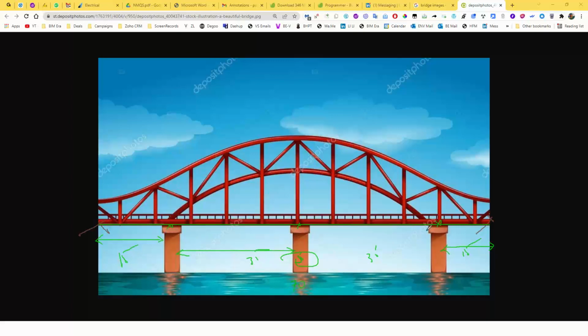Well, now this is the fun part. How to get these points? Using a point by parameter. We are going to see that now. I have a curve or a line, and I want to create a point at some parameter values. So this 15, this 35, this 35, this 15, we generally call these parameters. Remember, parameter here does not mean parameter names or anything. If you have certain values within a range, those numbers we generally call parameters, especially in mathematical geometry.